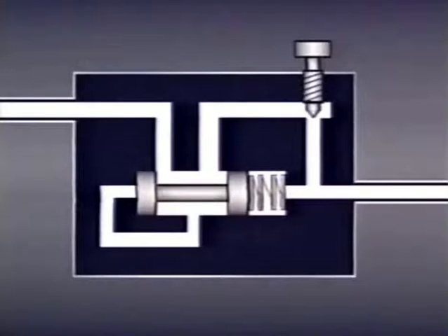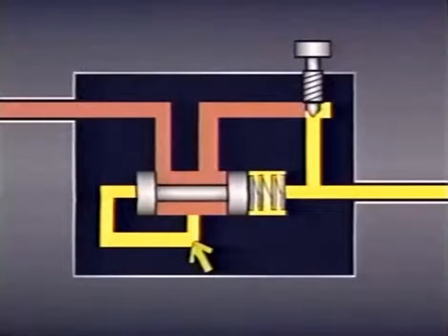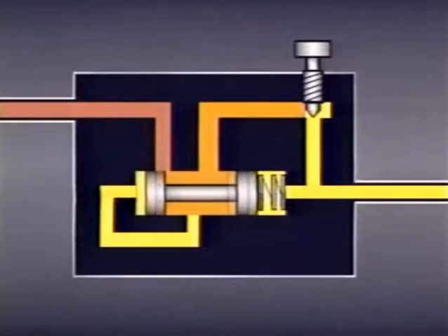It has a valve body with an inlet port and an outlet port, a needle valve, a spring-biased compensator spool, and two pilot passages. One pilot passage compensates for fluctuations in upstream pressure, and the other compensates for fluctuations in downstream pressure. The pilot passage that compensates for upstream fluctuations directs fluid pressure to one end of the compensator spool. As the spool moves, it blocks off part of the flow until pilot pressure equals the tension pressure of the spring.